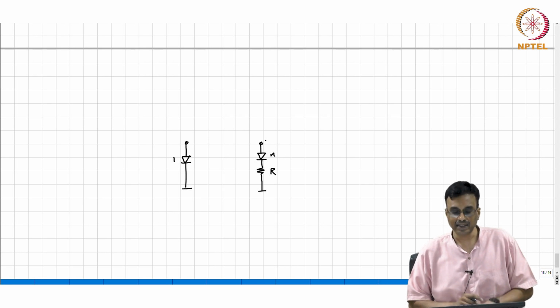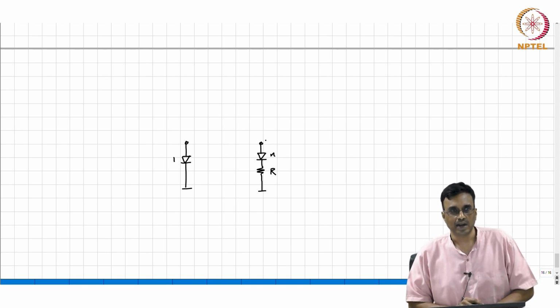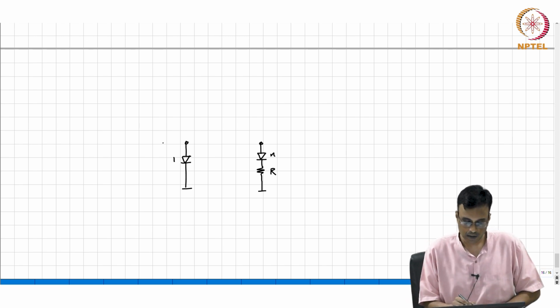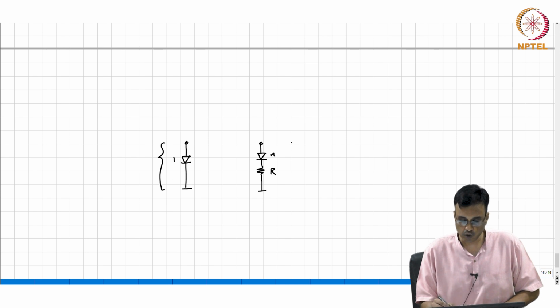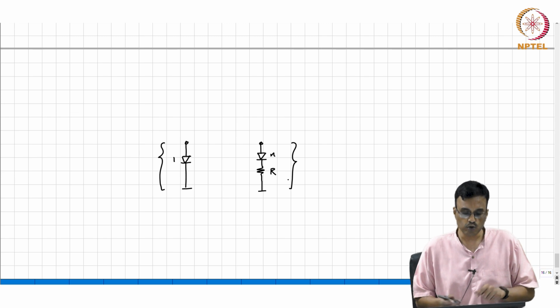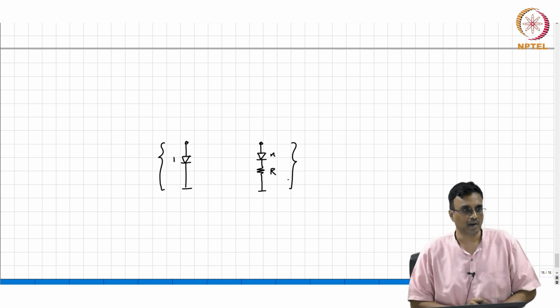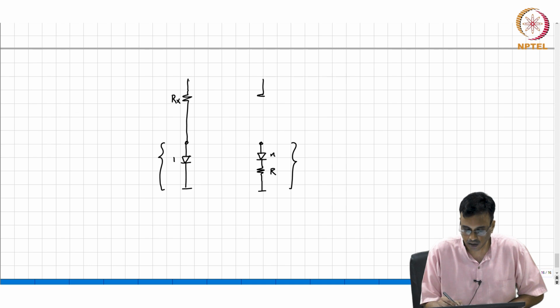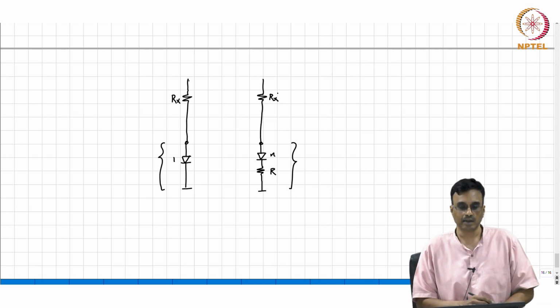So at the equilibrium point, at the magic point, the voltage across both these branches is going to be the same anyway, correct? So rather than use current sources, one could as well use resistors. Let's call this Rx.